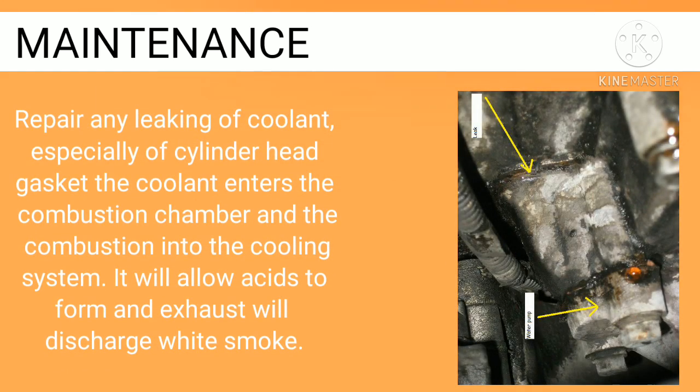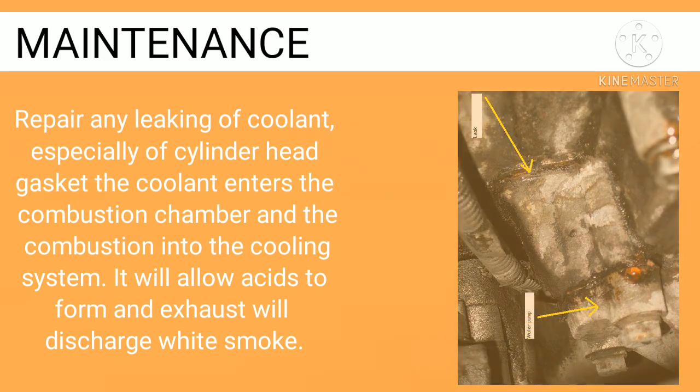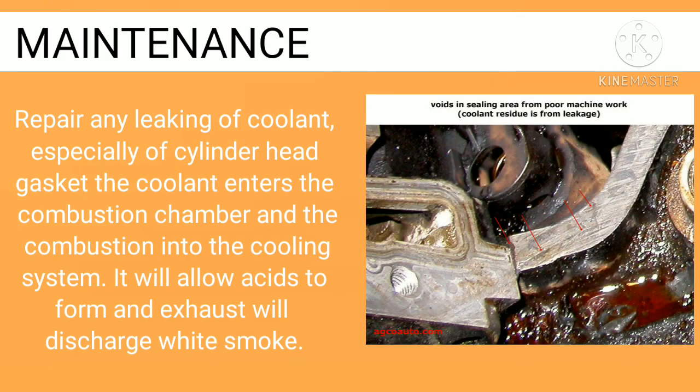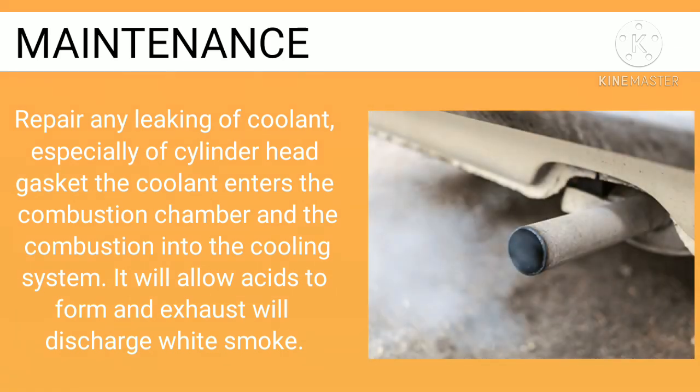Repair any leaking of coolant, especially of cylinder head gasket. The coolant enters the combustion chamber and the combustion gas enters the cooling system. It will allow acids to form and exhaust will discharge white smoke.